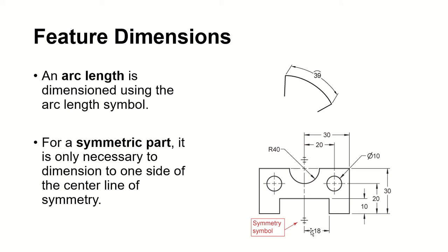The symmetric symbol, that's a new one in this diagram. You can see the little symmetric symbol right there. The symmetry is from here to here, so this serves as a mirror line for you. We put the symmetric label on the mirror line right at the center, because this side and this side equally have exact features.